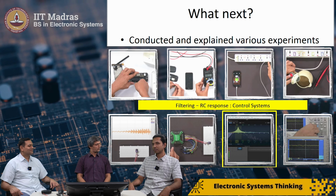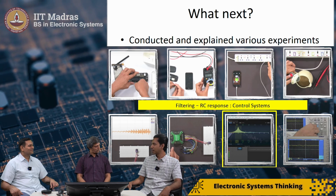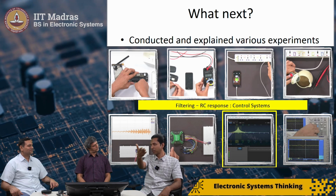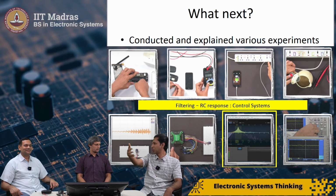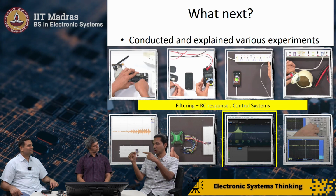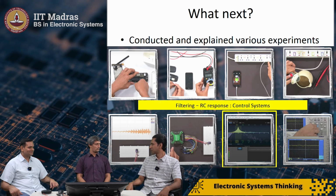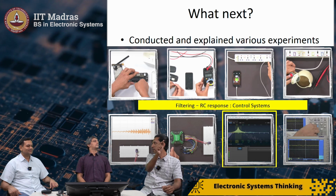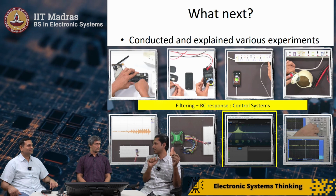Okay. So there is a temperature sensor that senses the temperature and gives maybe an analog voltage or a digital voltage to a unit. Okay. And then there is actively another unit making this room cooler. Okay. Now these two will have to be equal. Correct. So you have some feedback going to your control unit saying this is my current temperature, and there is another unit trying to achieve that.